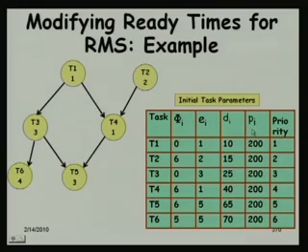We will just keep on assigning T1 is 1, 2, 3, 4, 5, 6. No, we are not really taking the deadline, we are just looking at their precedence, because unless a predecessor completes, if the successor starts, then it will block it if it has a higher priority. So for tasks at the same level, we look at the deadline. Just because they all have the same period, their priority would all have been the same, and with the same priority this will not work. Tasks can miss their deadline.